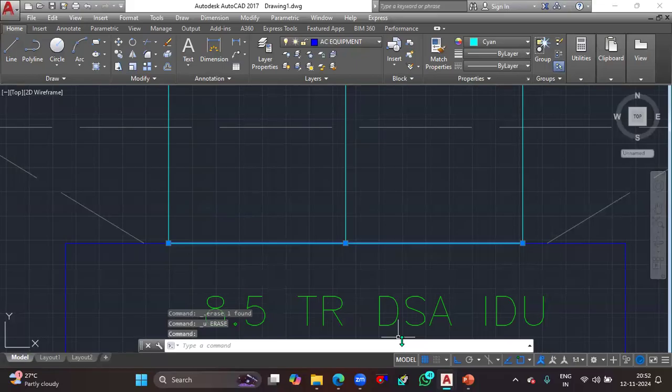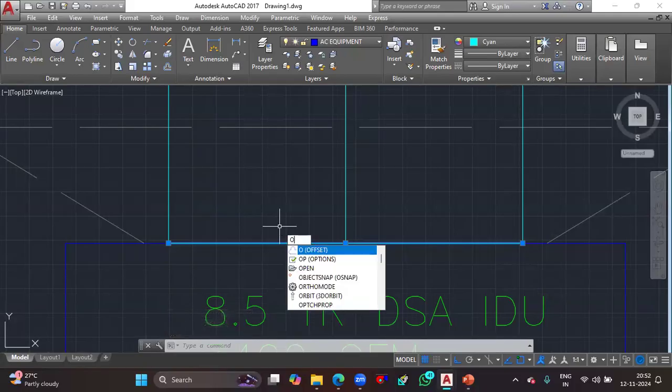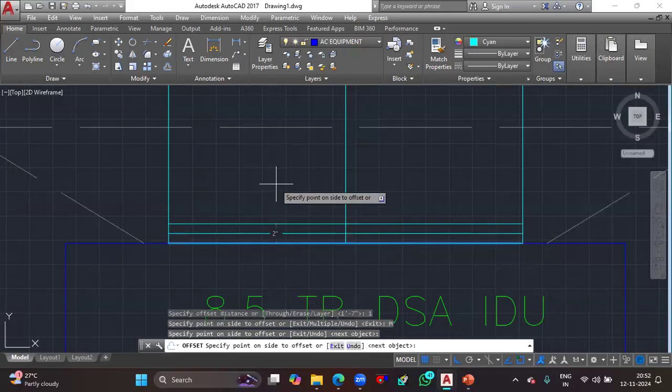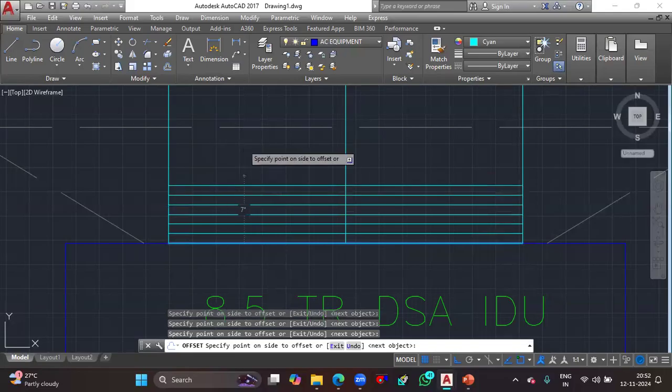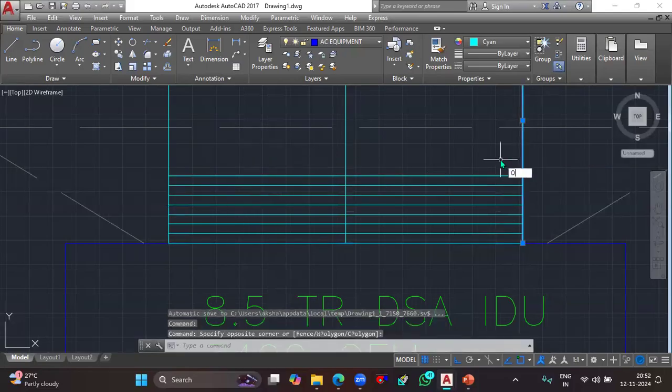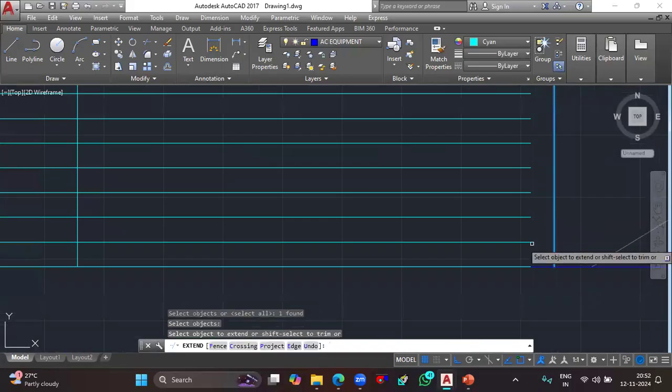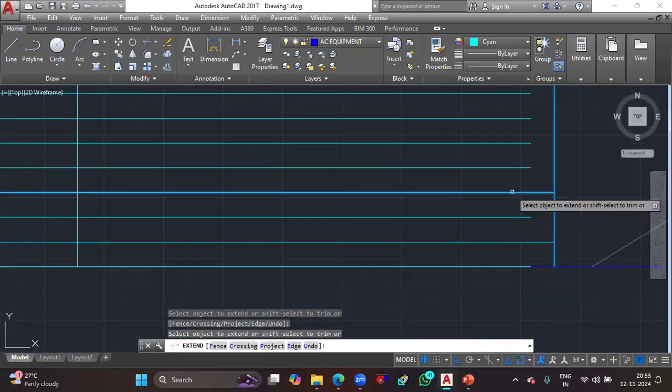So how to size the flexible canvas connection? Normally, the length of the flexible canvas connection is around 6 inches. Okay, so I'm going to offset this line specifically for 1 inch, and using the multiple command, you can see 1, 2, 3, 4, 5, 6, and 7. Okay, and once again, offset this also for 1 inch. Now once you got this one, just delete this line with the help of this extend command. Click this, it has to be the reference. And after that, extend each line alternatively like this. Okay, so that's it. So this line is not required though.